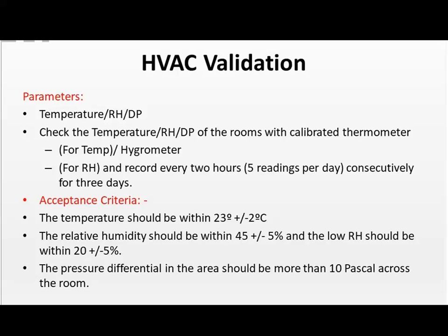The pressure differential is also something that they're going to be looking at, the pressure differential between the rooms, and they're measuring that in pascals. So the pressure differential in the area should be more than 10 pascals across each of your manufacturing rooms.